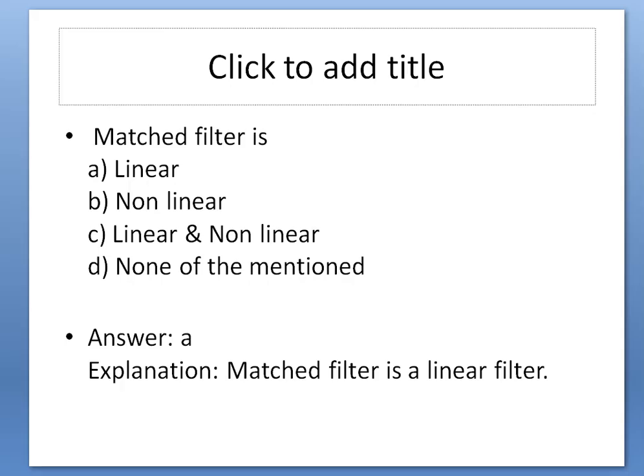We estimated the thermal noise using the Boltzmann constant, temperature and bandwidth, along with the receiver resistance in ohms. Finally we found the maximum available noise power by considering the maximum power transfer theorem. And we discussed some examples and some optional bits related to noise.